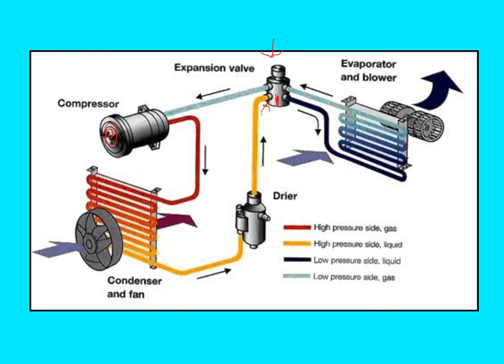So it's going to vaporize and leave there and go back out through this section of the expansion valve. This is pretty much a straight shot through, and it leaves the evaporator as a vapor, and it travels back to the compressor as a low temperature, low pressure vapor.